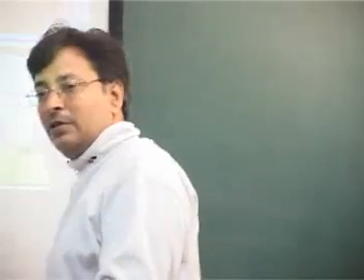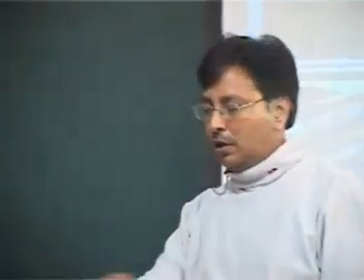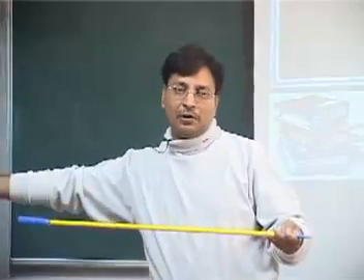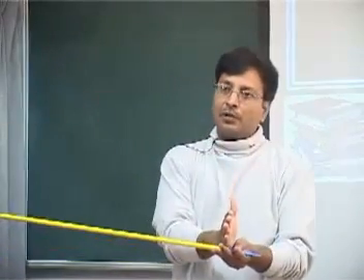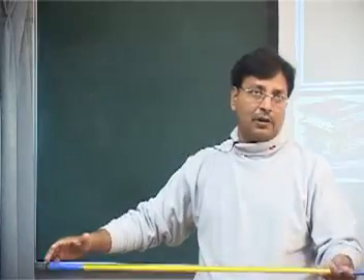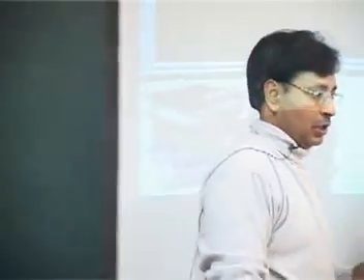If you want to measure the particulate matter at the auto exhaust, you put the probe, allow some residence time, and then put your filter holder at the back of this. You can't put a filter holder right on this one. So the sampling probe becomes very long. So that is what is shown here.